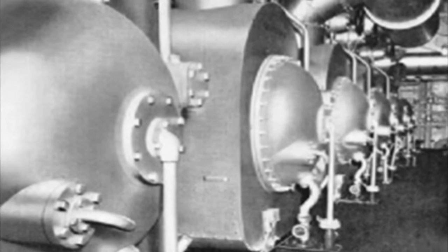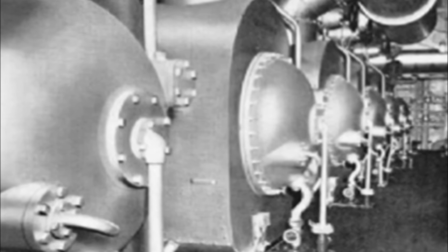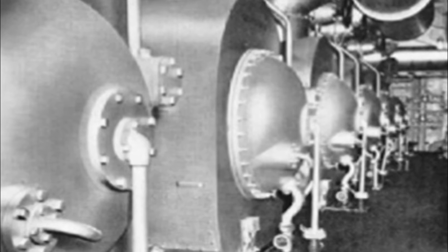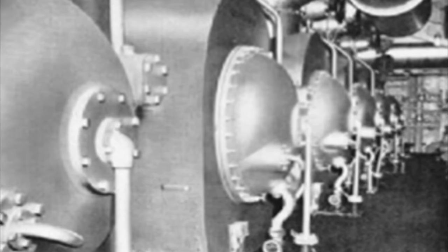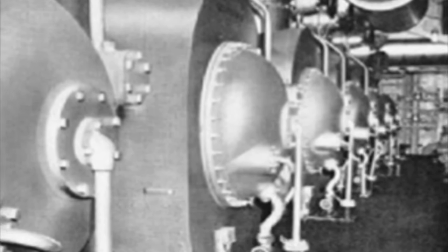The piston cycle rate of a free-piston engine depends on the weight of the pistons. The lighter they are, the faster the engine can run. Two engines with the same dimensions, but with cast iron pistons in one and aluminum pistons in the other, will have different piston cycle rates and, consequently, different power output.